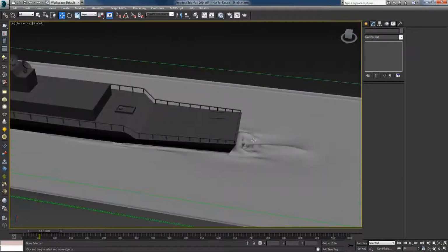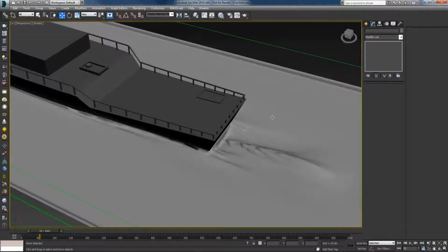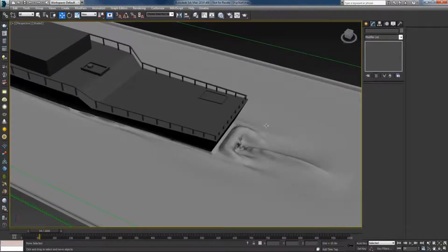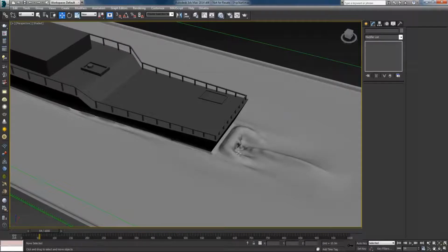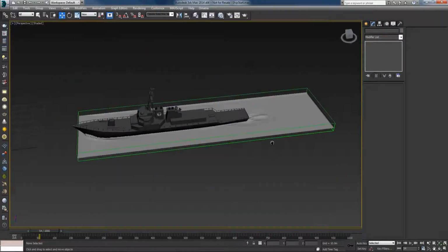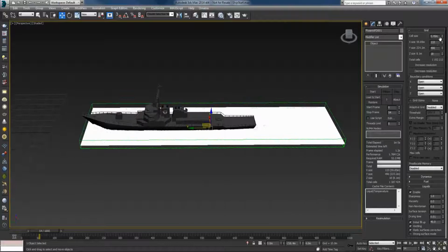Okay, so it's done, and this is with the liquid source at the bottom, and this was the previous result without the liquid source. And you can see it's definitely more interesting now at the back, and also some nice splashes will be created here. Okay, so now I think I can come back here and increase the resolution. I want it to be somewhere around 50 million, so let's try with 0.28.